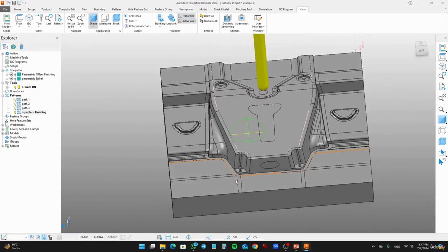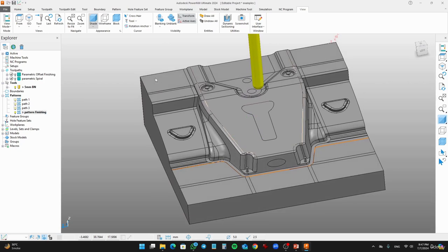So we have a curve, and we are going to apply a pattern finishing. In this operation, the cutting tool just follows your curve and cuts down the material or finishes a certain area which you need to remove using the curve. For that purpose, you need a pattern finishing operation. This will also help you if you want to do some engraving.